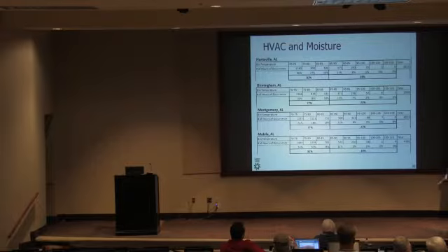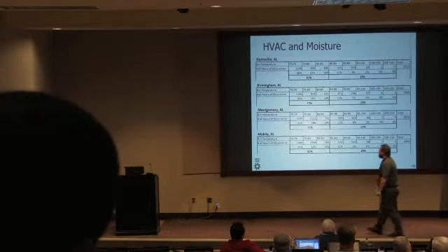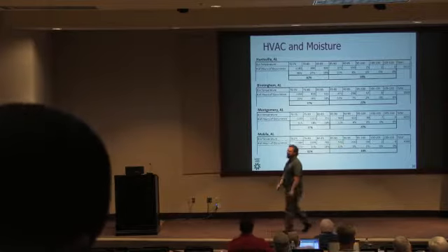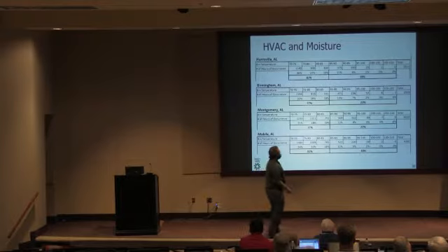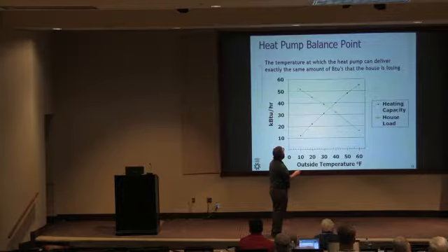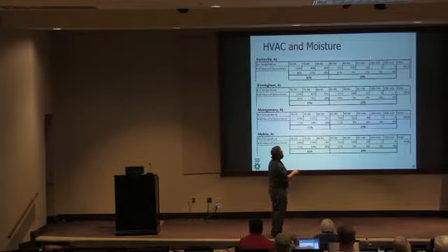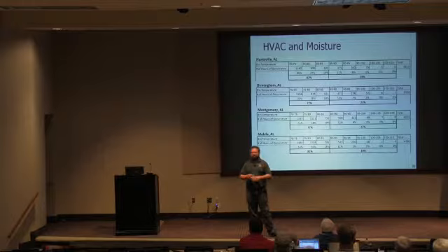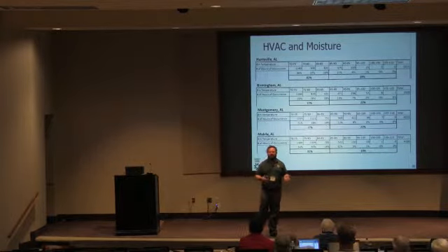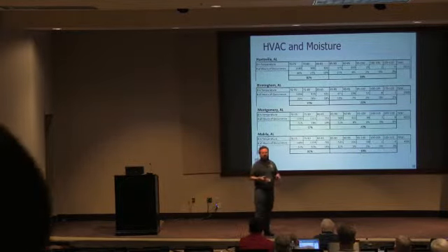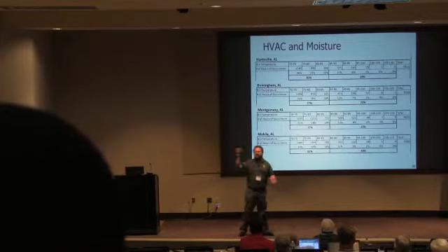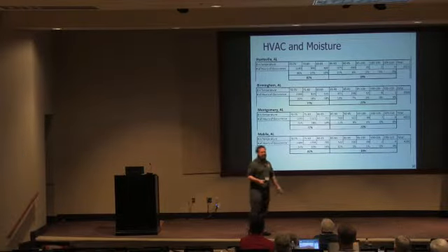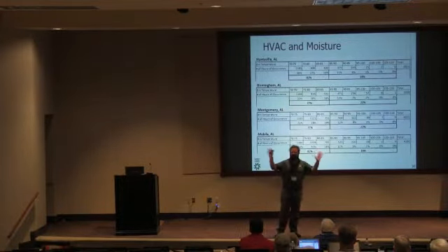So the real future of our HVAC industry says, I'm a contractor and I don't want callbacks. I don't want people calling me because on the one day of the year, or the 2 or 3 days of the year, that it is 97 degrees, and the thermostat is calling for cooling, and the HVAC system is running and running and running, and people are saying, I can't get to set point. I don't want that callback. So I want to oversize my equipment, because if I can always hit set point, then people are going to say, well, the system works well.